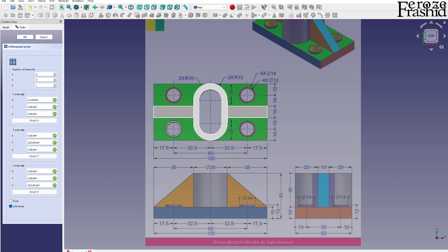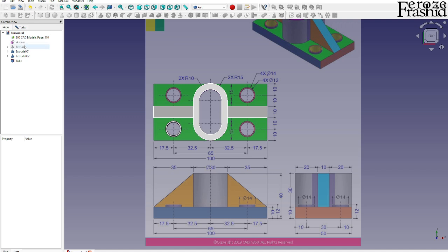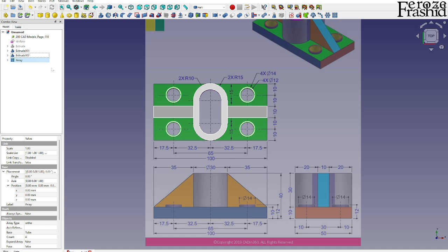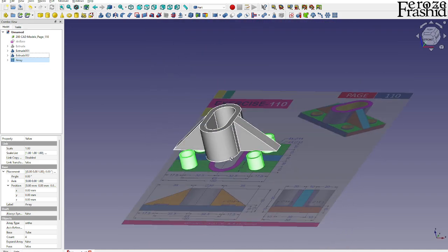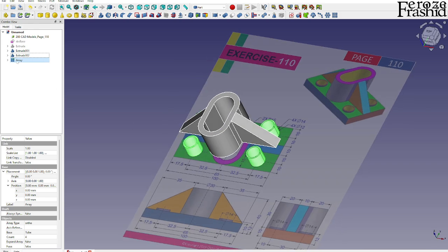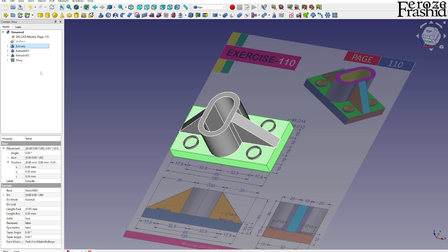And on y direction, 10 10 10, so that would be 30, and hit OK. Looks like we haven't selected this tube first, then hit OK. So that way that tube is replicated 4 times. That's a small amount of replication, so that's why I'm doing it in draft workbench. Had it been bigger, like 10 or 12 replications in an array, I would probably pick lattice2 workbench.